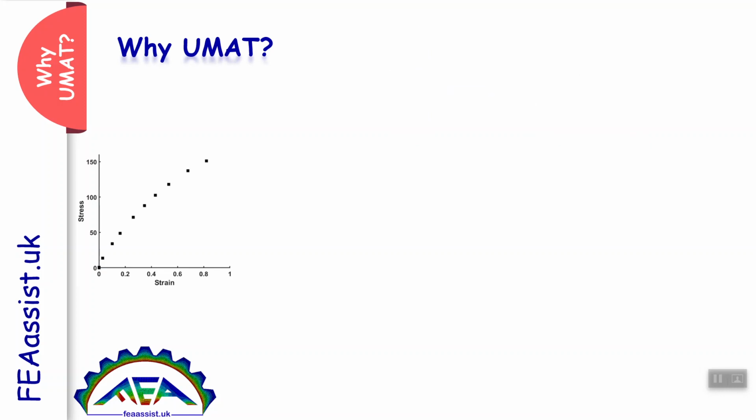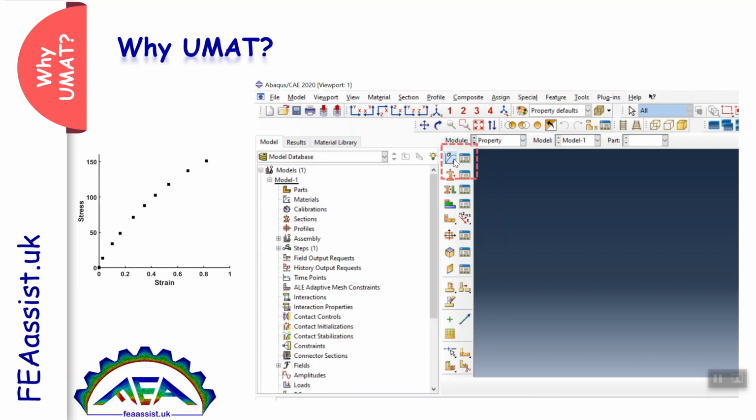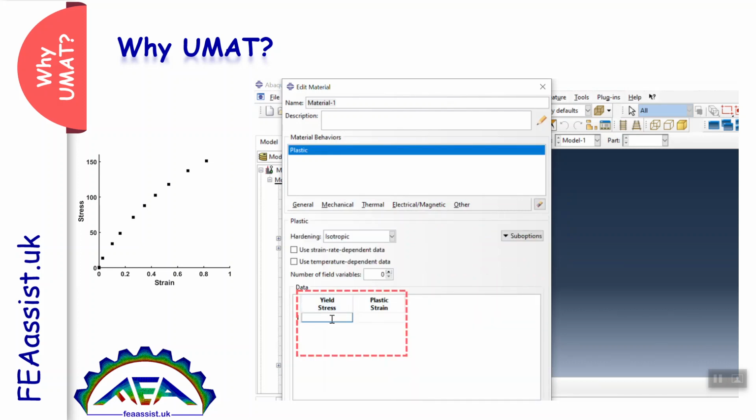The first strategy is that you have some of the points of your stress strain behavior from lab or from published experiments. You can easily go to Abaqus, to the property, define a new mechanical behavior, plastic behavior, and enter those points like this.